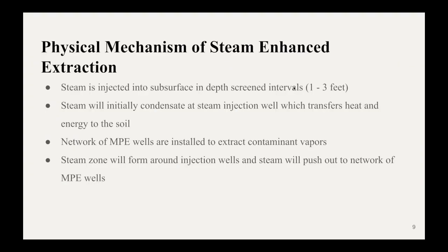So the last type of thermal remediation that we will cover in this presentation will be steam-enhanced extraction. Steam-enhanced extraction is based on the method of injecting steam directly into the subsurface. Steam is injected in depth screen intervals of 1 to 3 feet, but it'll typically just be 2 feet.